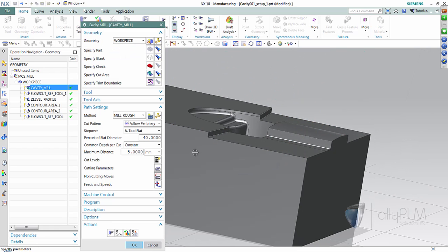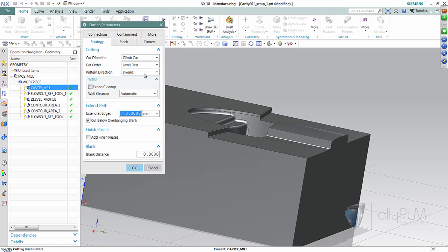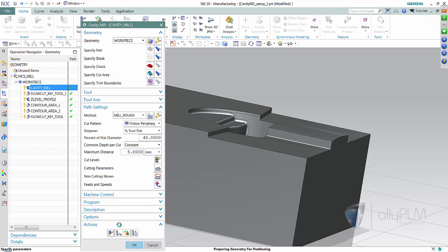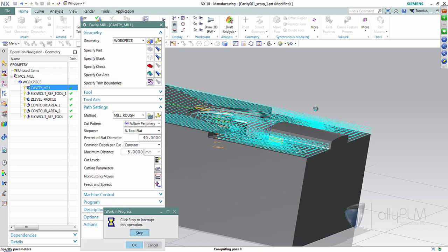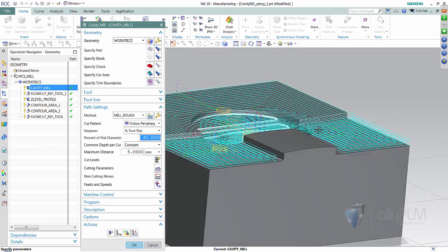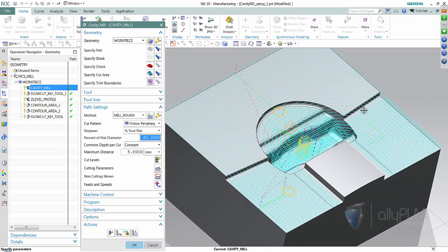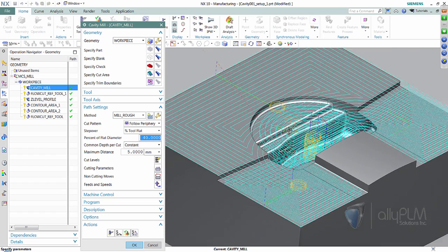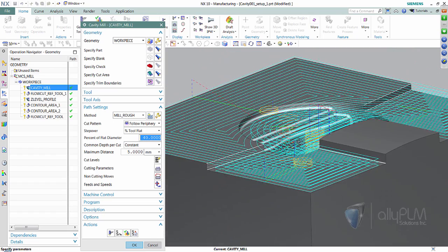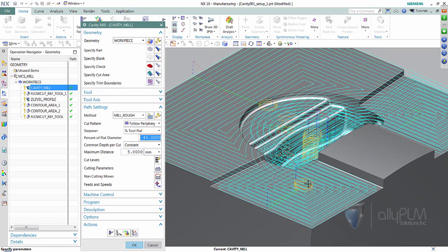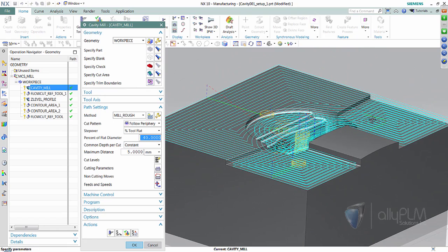The other option that we have is we could do an outward option. So I'll go ahead and regenerate that with the outward option, and as you can see here, it will not approach from the outside since we've told it to work its way outward. So notice we have all of these extra ramp moves that are really unneeded when we have an open area like this.